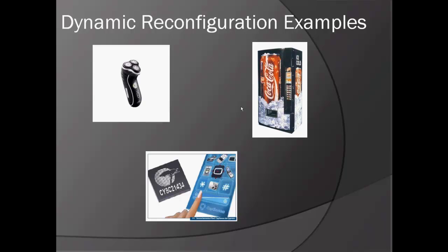At predetermined intervals, the device will reconfigure itself to participate in inventory activities, such as calculating totals of products sold, determining need for additional products, and participating in modem operations to communicate with a central resource. Both of these functions can independently fit inside the PSoC, but they cannot both fit at the same time. Since the operations occur at different times, dynamic reconfiguration can be used.